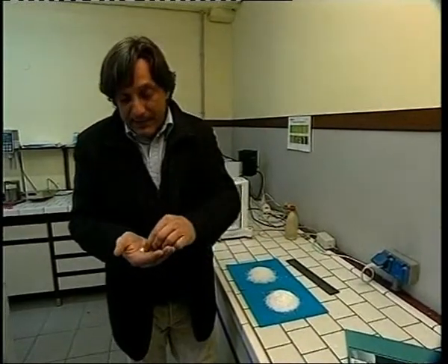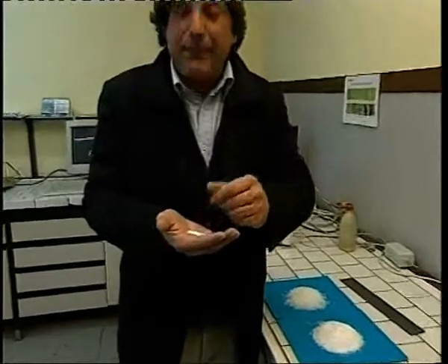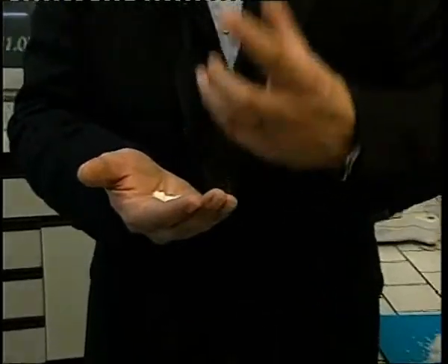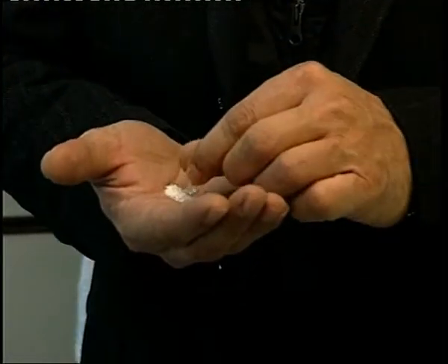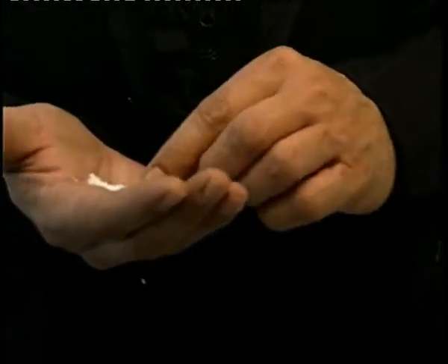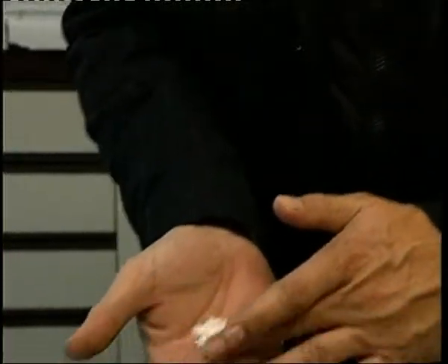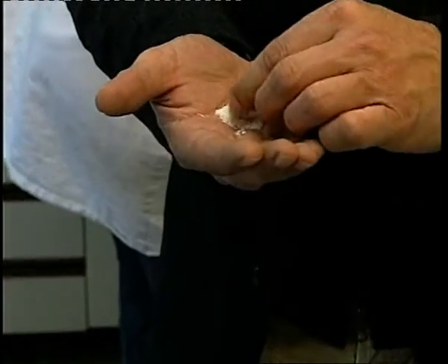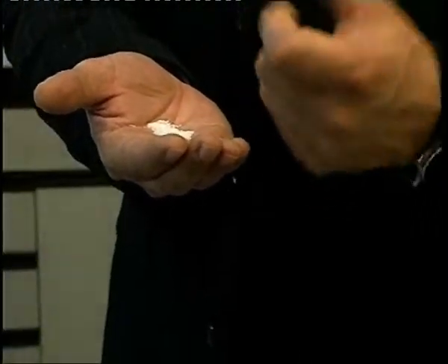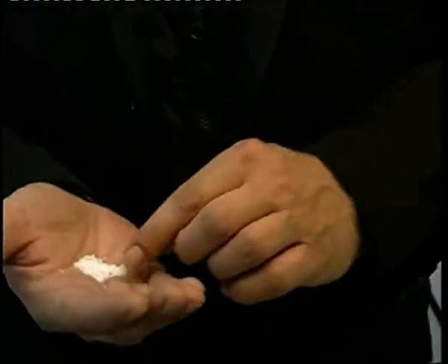SBS resin, an elastomeric resin, makes the membrane particularly flexible and malleable. It's a synthetic thermoplastic rubber which, when mixed into the bituminous polymer membrane's compound, provides qualities that are very useful in cold climates or whenever an extreme elastic membrane is required.